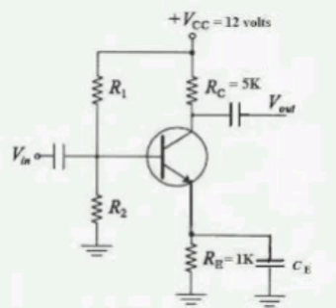Calculate the resolution of the instrument in millimeters. Sensitivity of LVDT equals output voltage by displacement, that equals 2 into 10 power minus 3 by 0.5, that equals 4 into 10 power minus 3 volt per millimeter. Sensitivity of the instrument equals amplification factor into sensitivity of LVDT, that equals 200 into 4 into 10 power minus 3, that equals 0.8 volt per millimeter, that equals 800 millivolts per millimeter.